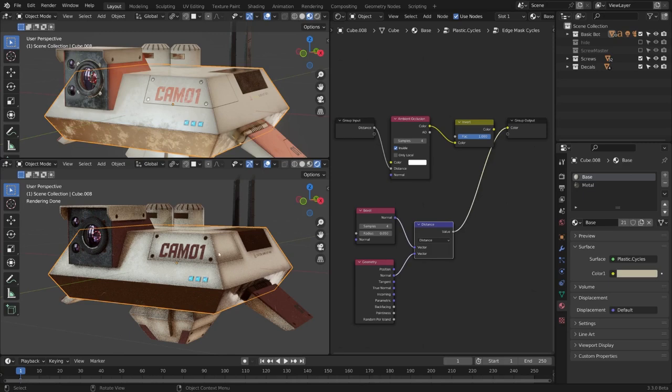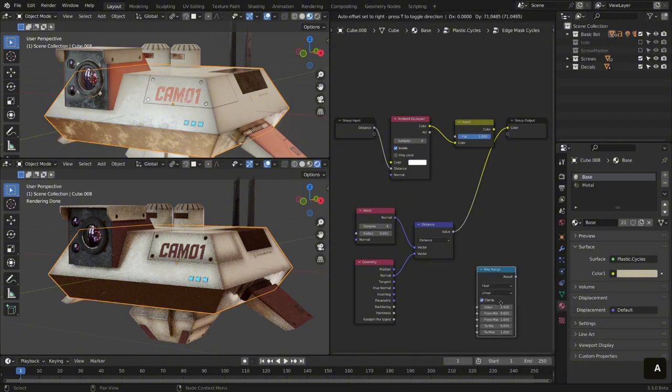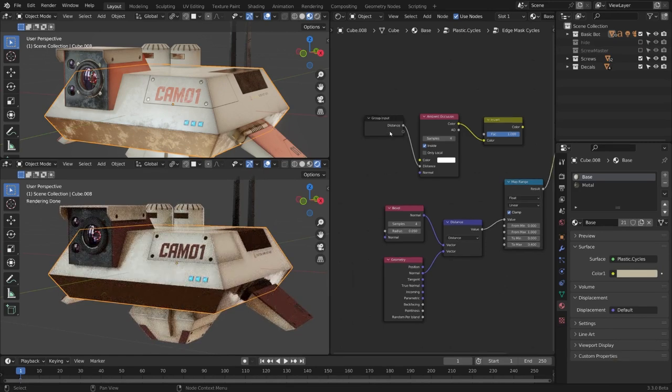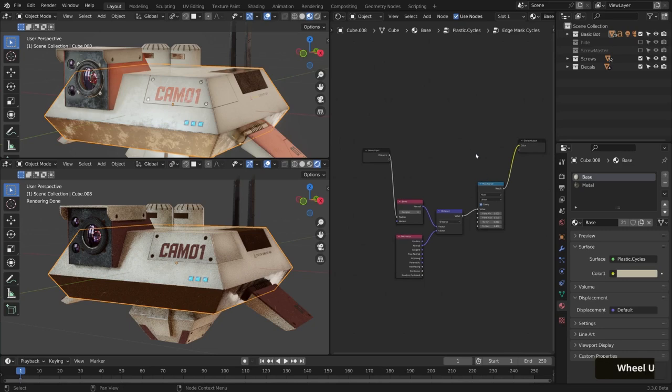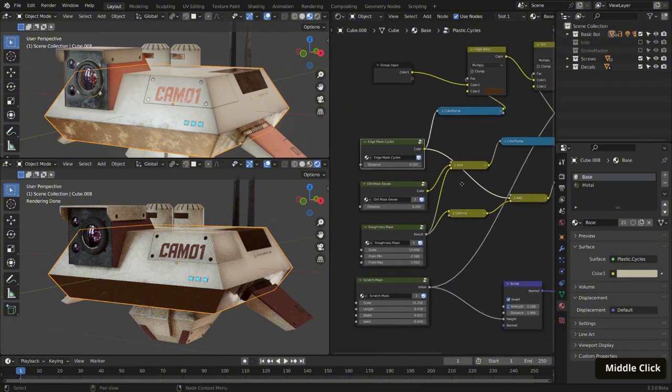Although this is quite strong, so I think we can introduce a map range node and just turn down the output to 0.4. And again, we can use our distance input here to control the radius. Okay, looking good. We don't need these two nodes anymore, so we can just hit X on the keyboard to remove those, and then Tab to jump out. And while we're at it, let's also protect our new shader, just in case we drop it out for some reason, and look at updating the other materials.